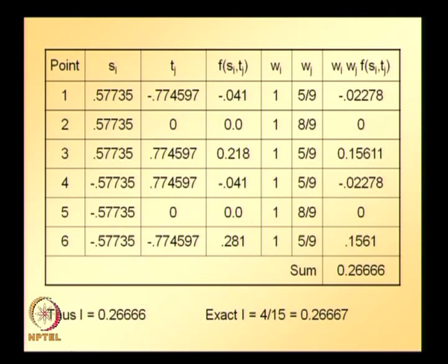So, so far, as a part of this isoparametric quadrilateral element, we have seen how to derive shape functions for 4 to 9 node quadrilateral elements, and we also looked at the isoparametric mapping concept for 2 dimensional elements, and numerical integration for evaluating integrals over 2 dimensional domains. So, now we are ready to develop element equations by taking any one of the quadrilateral elements.